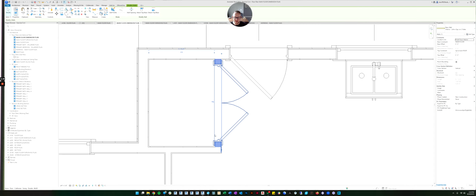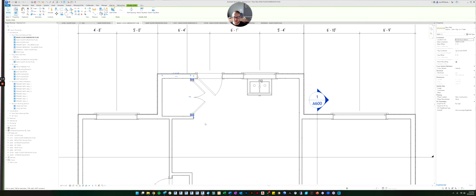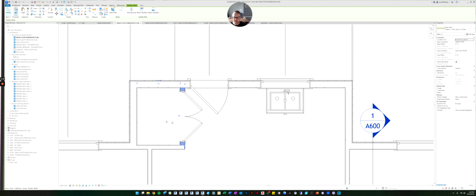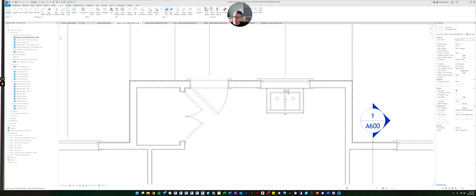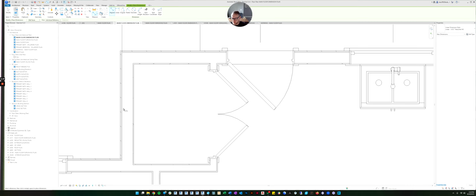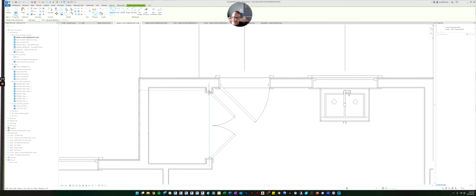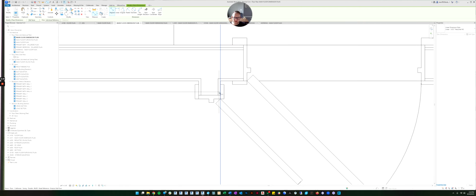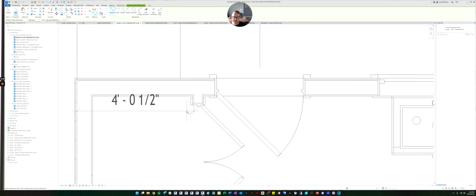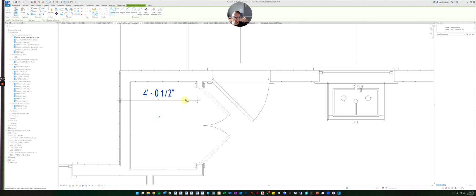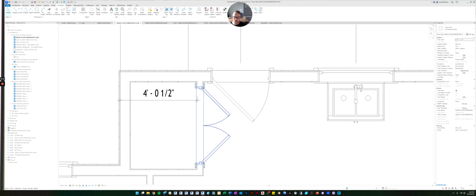But do they know where to set this wall? Now this wall, they don't know where to set because there's no dimension yet. So we'll dimension this. Again, I'll go from the outside face of the wall, and on the inside walls, you can pick either side of the wall. You just consistently want to pick the same side. So we'll do the inside of the wall.